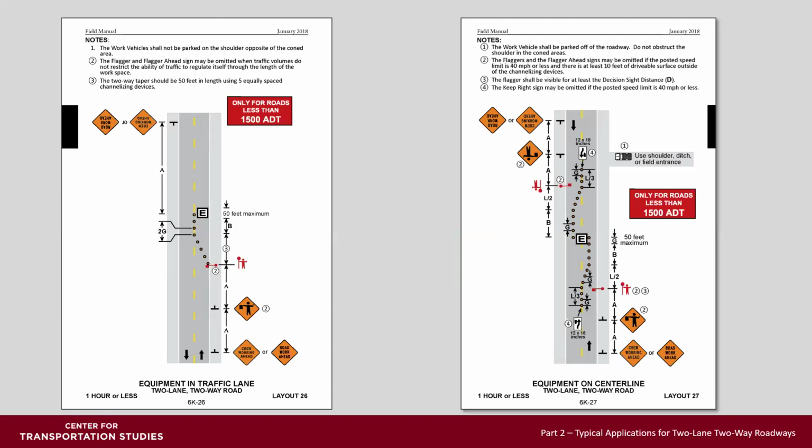Layouts 26 and 27 were developed for survey operations, something that goes relatively quick. You will note that it's 1 hour or less to complete this work. It's minimal traffic control. It's only to be used on roadways with less than 1,500 vehicles per day.